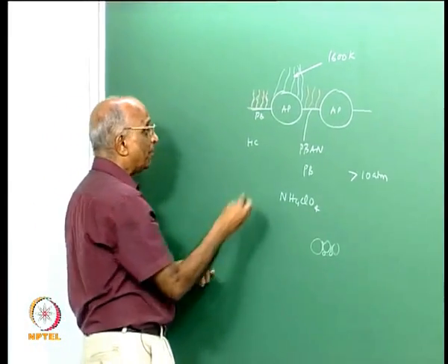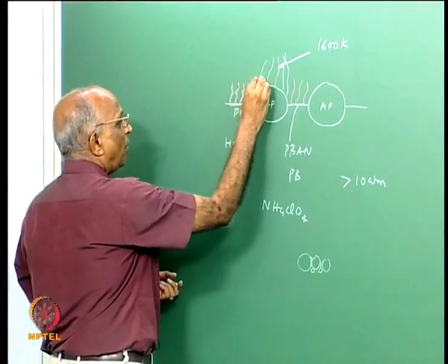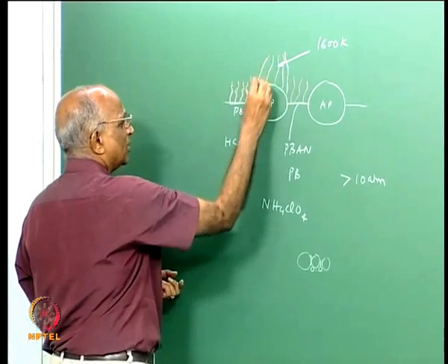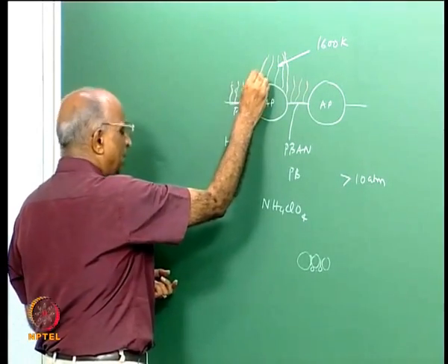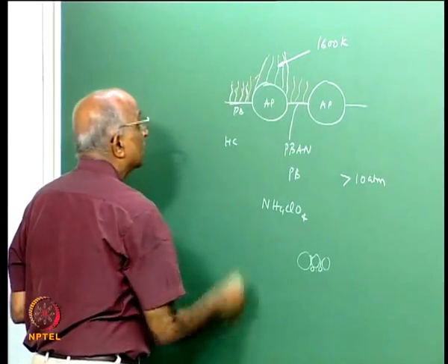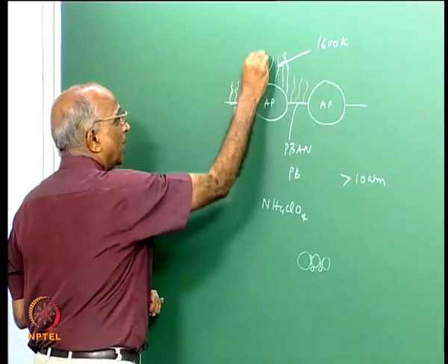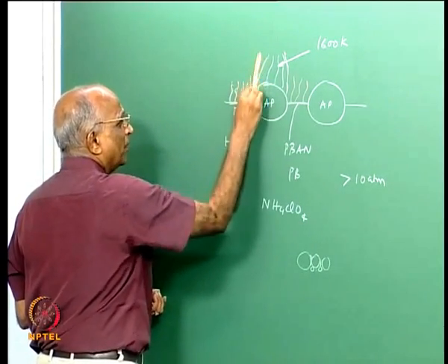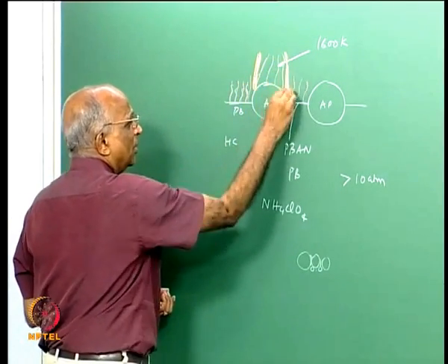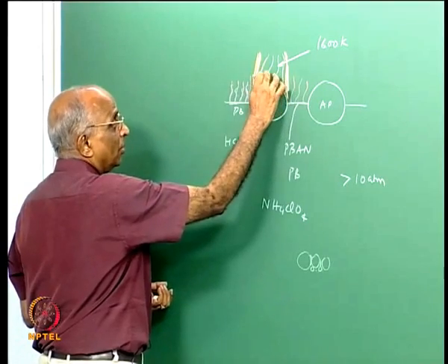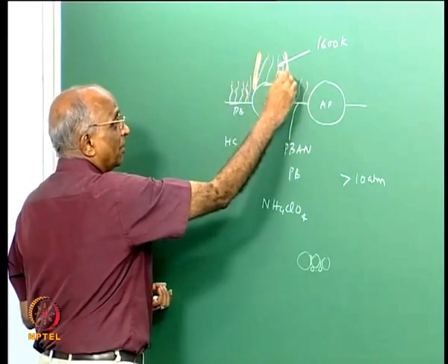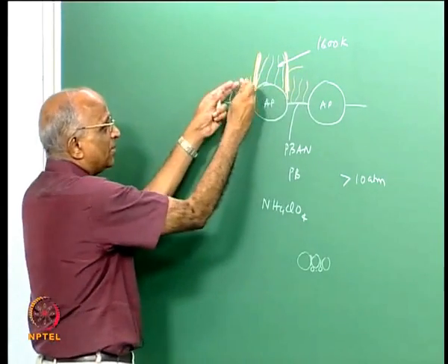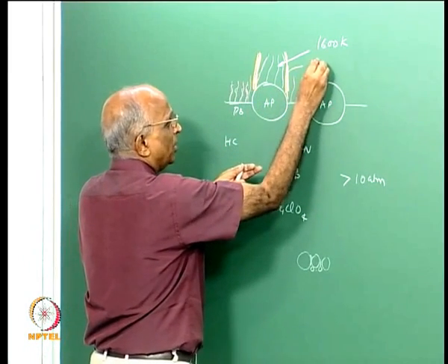Therefore, I have fuel vapor coming over here, I have oxidizer vapor which is terribly oxidizer rich, and when the fuel vapor meets over here, I could have something like a zone wherein again burning will take place between the oxidizer rich flame which is coming from AP, and this will be something like mixing taking place or a mixing dominated combustion.